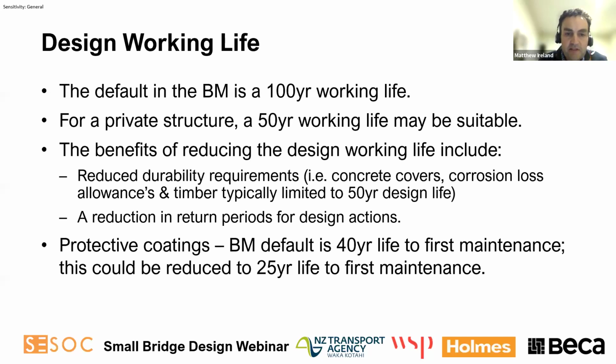Another thing with the bridge manual is that the default for protective coatings for steel elements is a 40-year life to first maintenance. Again, this could be reduced. Typically, you'd probably go for a 25-year life to first maintenance if you're going to reduce it. Again, that could make you some initial cost savings, but in the long run, it may not. Next slide, please.